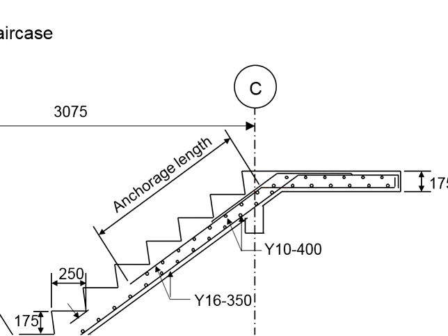The same principle applies to the longitudinal reinforcement from the flights. Again, you would like to keep the reinforcements straight as long as possible. That means when the reinforcement of the flights enters the landing, it should continue its path until reaching a state where it will have to bend, so that it fixes the landing here.